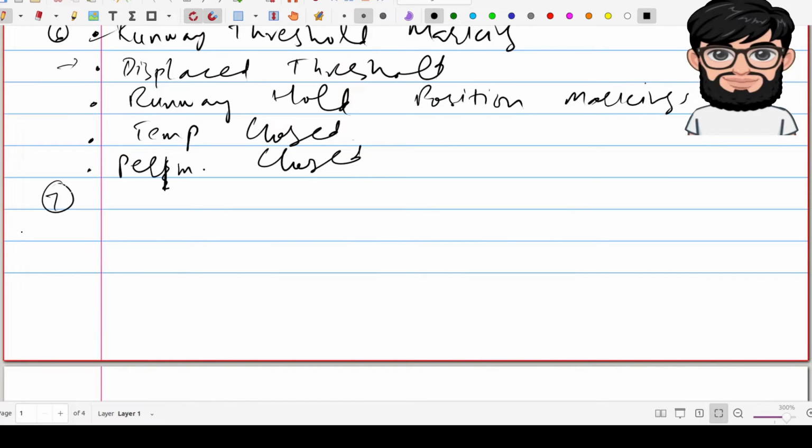Okay, what are the different methods a pilot may use to determine the proper runway and traffic pattern in use at an airport without an operating control tower? So if we do not have ATC available and we want to know the traffic patterns and the proper runway, first thing is that there can be a Unicom station, right? And an advisory may be obtained, which will usually include the wind direction, the velocity, and everything like that.